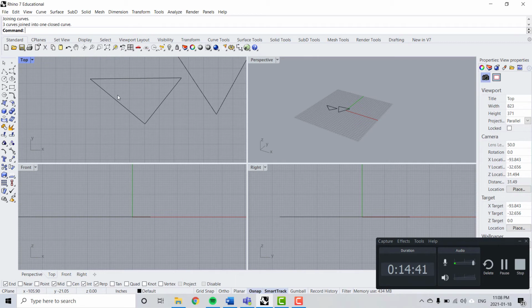I'll get into the importance of this a little bit more when we jump into 3D, but for now, just know that it's important to make sure your snaps are on, make sure that your endpoints touch, your lines are meeting correctly. And try to always have closed curves for the most part.